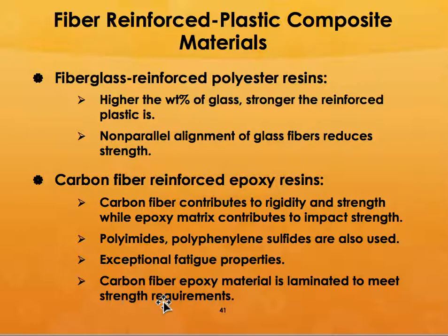In carbon fiber reinforced composite, you can also find matrix materials such as polyamides or polyphenylene sulfides, especially if you require high temperature exposure to the composite.